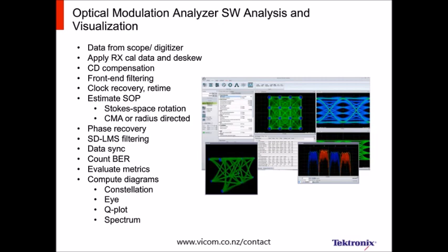So you might need to turn on adaptive filters. As soon as you turn on adaptive filters, you're complicating things a little bit because this is a real-time filter that's being designed by an algorithm to compensate for all frequency domain impairments that are present. So that will include polarization mode dispersion, but it will also include, say, cable loss in the transmitter.